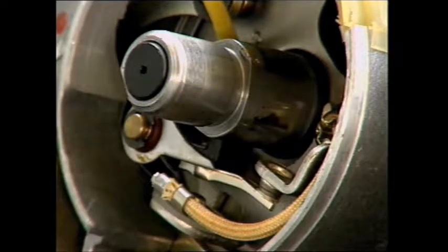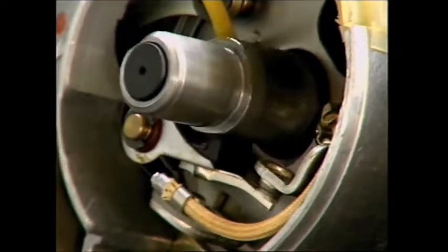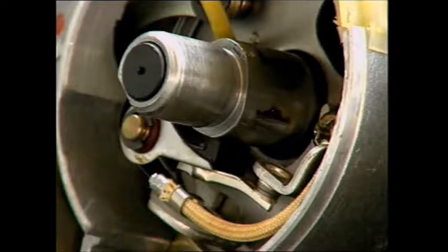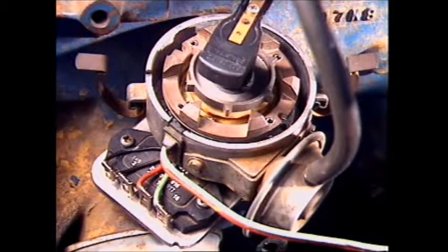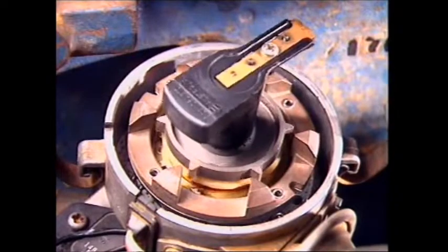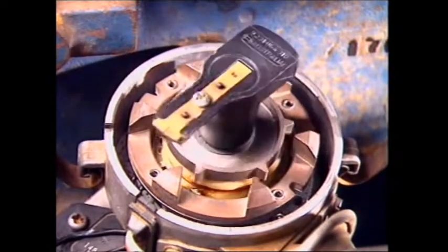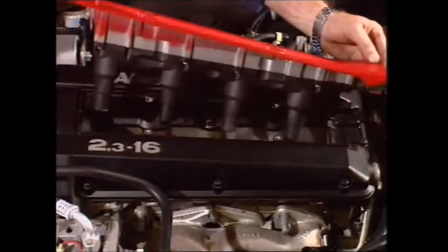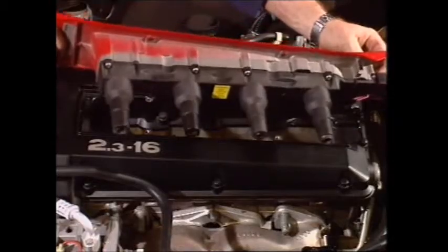There are three general types of ignition systems. Breaker ignition uses contact breaker points in the distributor to initiate the spark. Electronic ignition doesn't need contact points. When a signal is received, triggering occurs through transistors in an ignition module. Direct ignition has no distributor and uses coils to supply high voltage direct to the spark plugs.